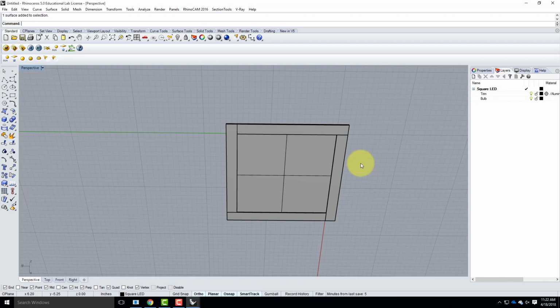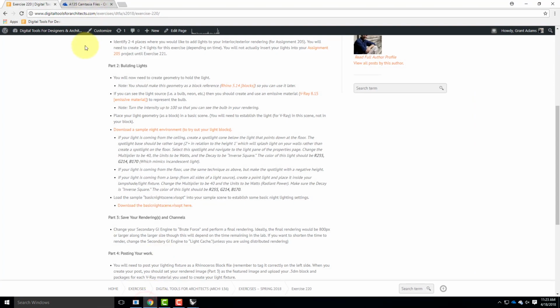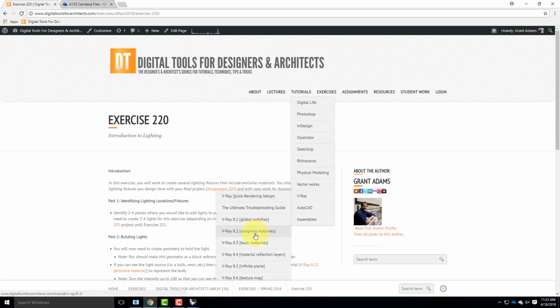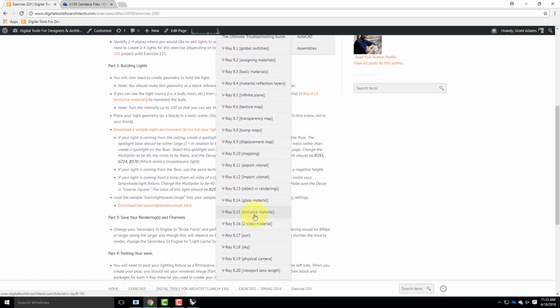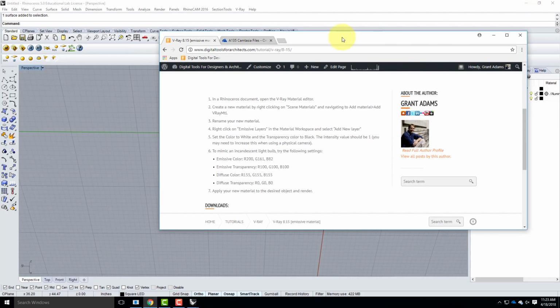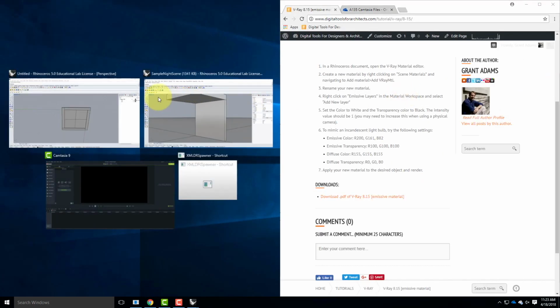I have a tutorial written up on how to do it. It's V-Ray 8.15. And so I'm going to pull that one up as a reference because there's a few numbers that I can't remember off the top of my head. So let me go into my tutorials. Let me go to V-Ray, and we'll scroll down here a bit to 8.15. There's the emissive material. And this is going to walk us through how to create this particular material. You could save it after you create it onto your flash drive so you can use it over and over, though creating it's pretty fast. So I'll leave this one, let me just stick it over here for just a second.